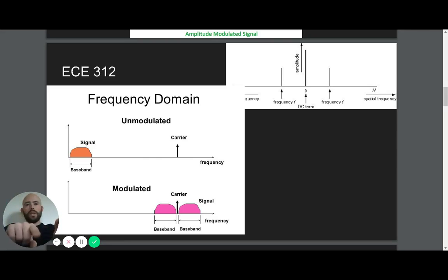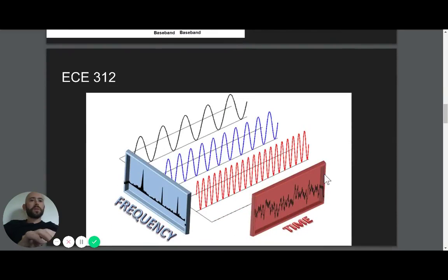So as we're demodulating, we now have this baseband that is centered around the carrier. If we multiply by another carrier, that carrier is doubled. Well, it's multiplied again, and you get a copy that's going to be back near the baseband. And the information that we want is now back where we need it, and then we use a series of filters to get the information that we want.